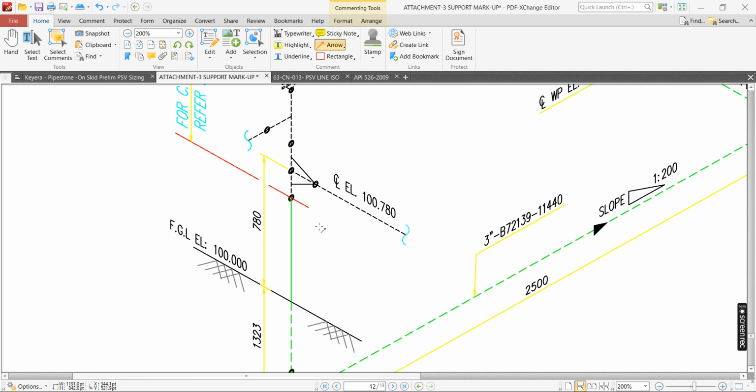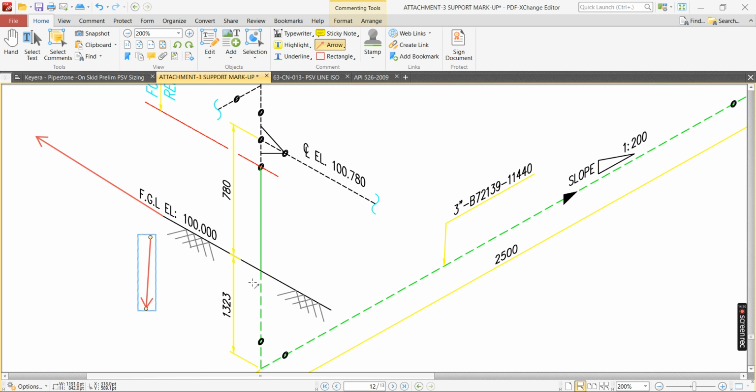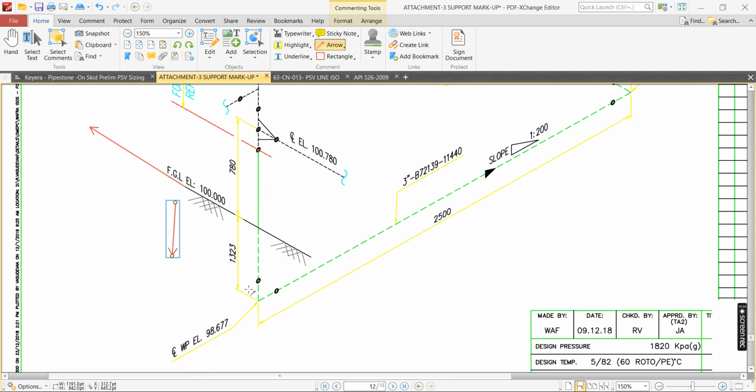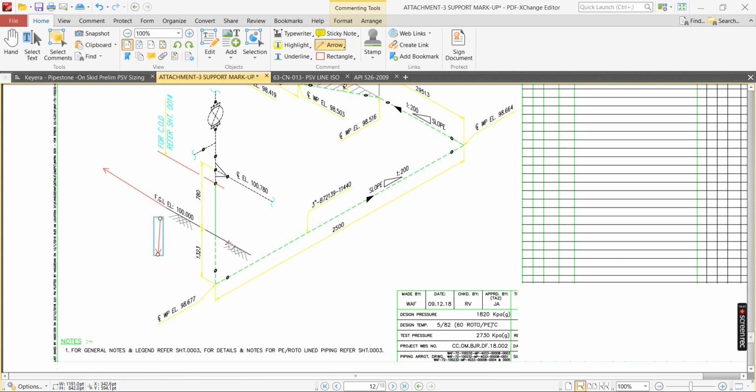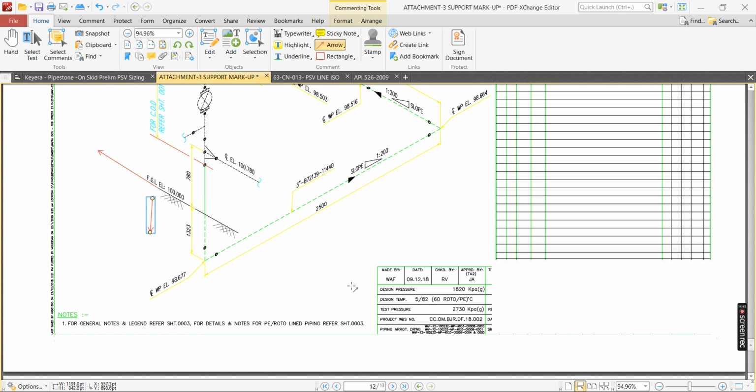So you see after this, this is finished ground level. Finished grade level is 100. So this is your ground level. This is your ground level. So below this, it is buried. You see, the isometric line has been shown in dotted lines. That means it is going underground. That is the buried line. From this portion onwards, the line is buried. It is filled with soil.